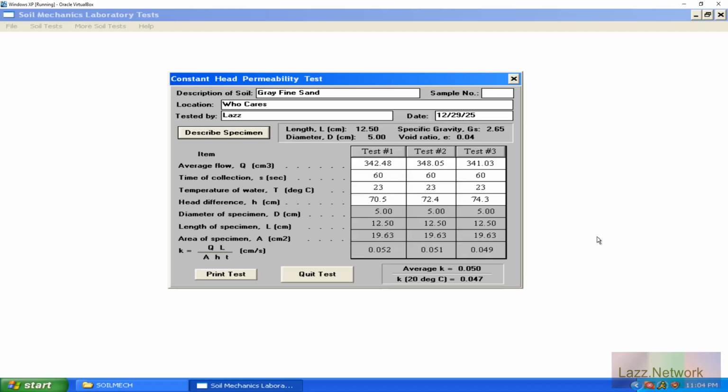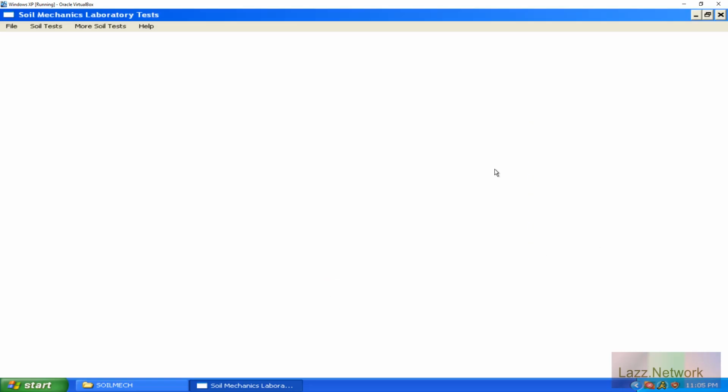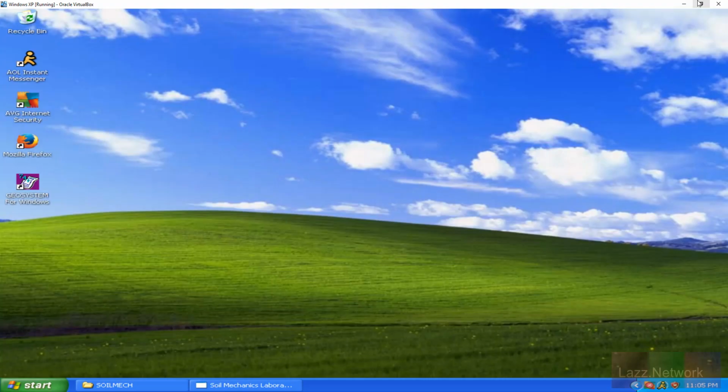And we did it both ways, whether our device had manometer ports or not, which, granted, for the example that I had, the head heights were going to be the same because I just made it that way. Really it was just changing the volume to see how much of a difference we were going to have for our flow rate. So yeah, there we go. That is constant head permeability.